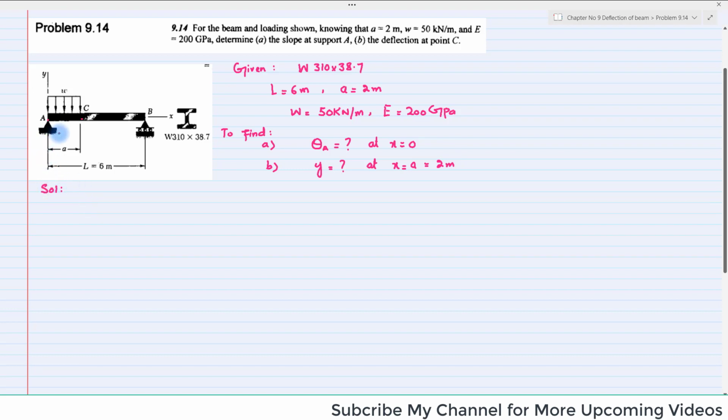First of all, you know that this is the beam, so you have to draw the free body diagram and find the unknown reaction forces at point A and point B. Let me draw this beam. This is point A. At point A the reaction force will be RA, and at point B the reaction force will be RB. Clear?